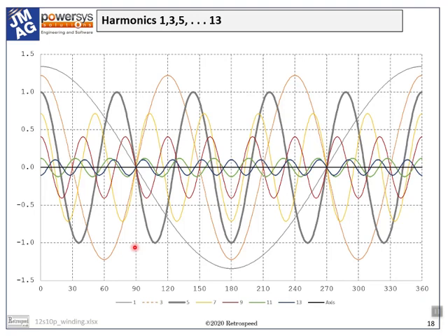Under balanced conditions, if there's any imbalance, the third harmonic may well be large enough to cause trouble in the core in the form of torque ripple or other parasitic effects. The higher orders, the 11th and 13th and so on, are becoming smaller as their order increases, and so we may be able to ignore them as long as they don't coincide with the mechanical resonance or cause excessive eddy current losses somewhere.